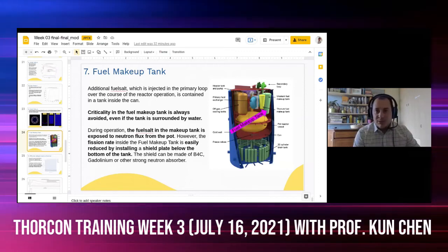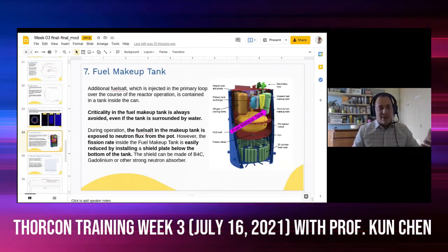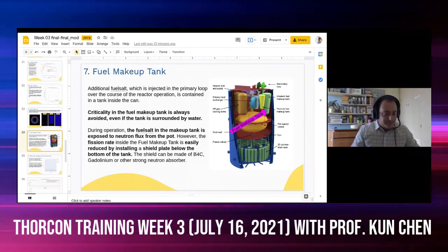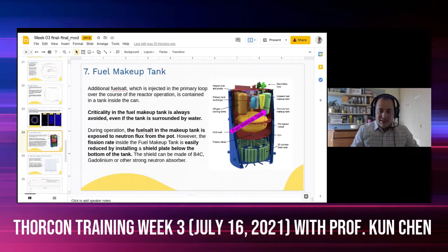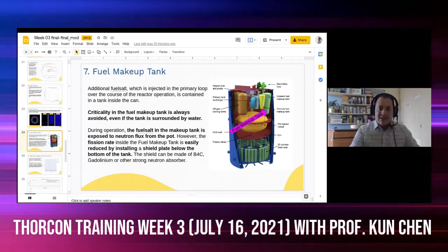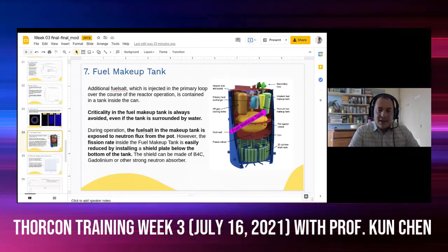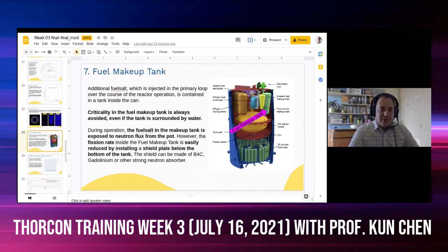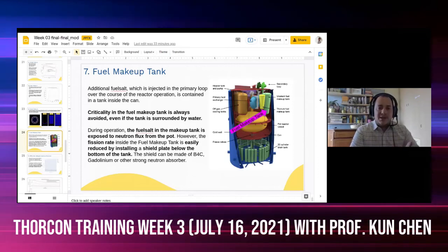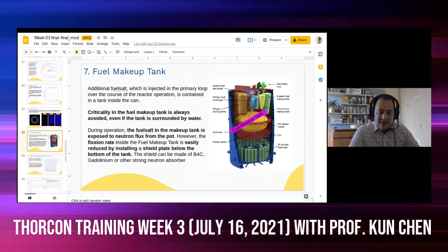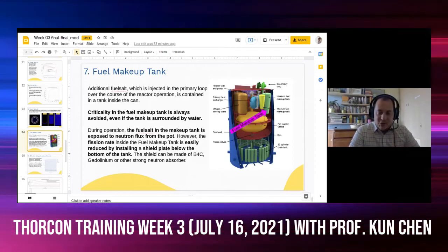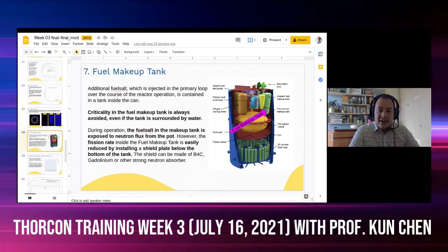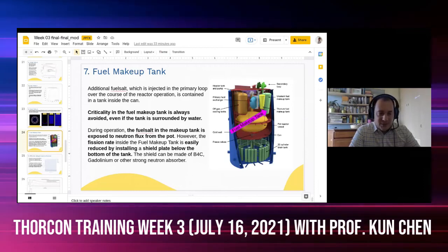One of the cold areas of the primary loop, as you might imagine, is the primary heat exchanger. So it is expected that a relatively large fraction of non-soluble fission products will deposit on the primary heat exchanger, thus effectively reducing the overall heat transfer coefficient.